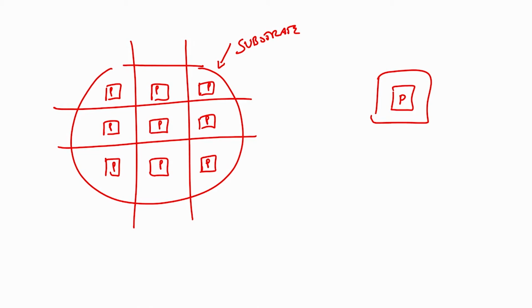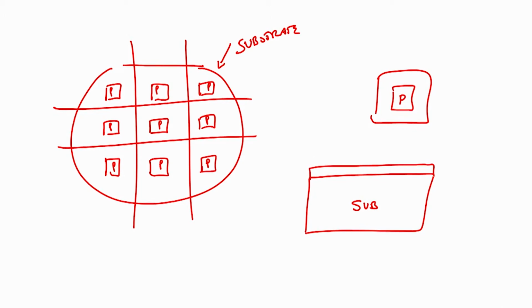So, how our diced wafer looks under the microscope, we will see the inspection of that. Also we will look at the CNT sensing layer for the fabricated sensor. What does that mean? Let us say I will just show you in terms of blocks. So, you have a substrate again, right, and on the substrate you have a heater. On the heater you have interdigitated electrodes. On interdigital electrodes you have a sensing layer.